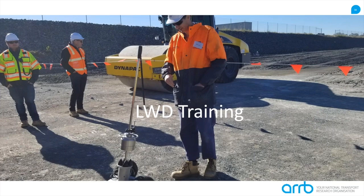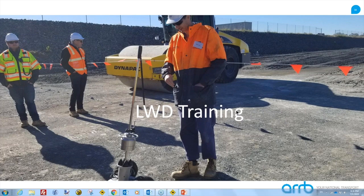And to top it off, with this IC roller we are getting the response from the accelerometer and having the visual feedback inside the cabin of the roller compactor. But as an additional add-on, we are doing some spot testing across this site. One of the machines that we used was the lightweight deflectometer, which is basically you drop a dead weight on the ground, and it gives you a response from deflections to indicate the stiffness of the ground.